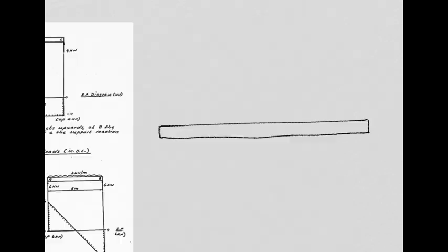And then we get to the end over here and we encounter a 4 kilonewton upward effect, which takes us from minus 4 conveniently back to 0, which is correct because for this simply supported beam, the shear at the ends is 0. So that takes us back to 0, and then we know we are correct as well.